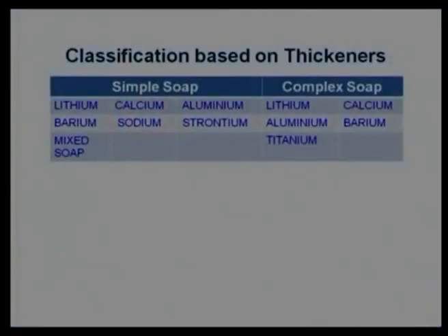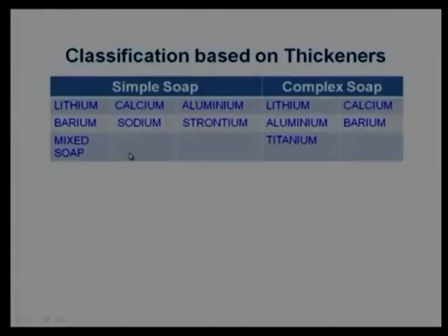Coming to the thickener, we say thickeners can be defined in a number of categories, which we call soap based, according to the process in which the thickeners are made to convert into grease. They are generally simple soap base, complex soap base, and there are other kinds of non soap base also, where clay is used to make grease. However, the soap based greases are more popular or most commonly used unless we require a high temperature application or severe load applications.